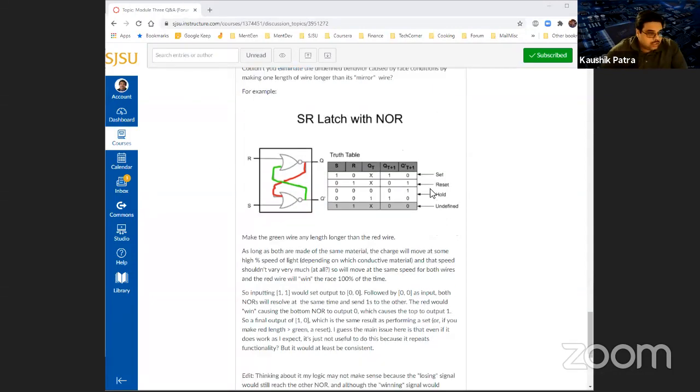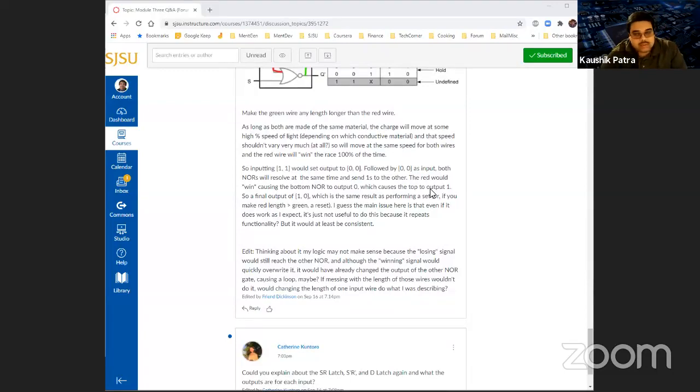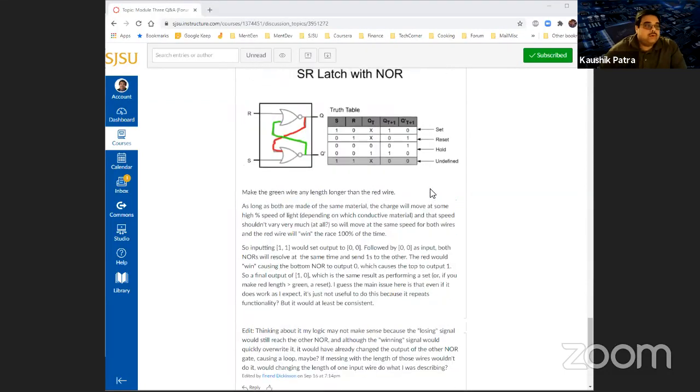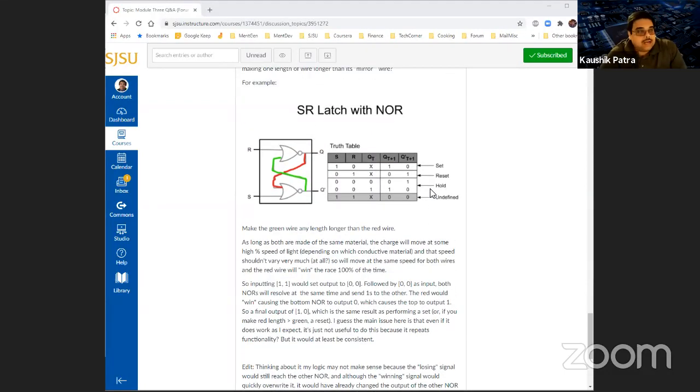That's good thinking. In fact, in asynchronous circuits, some of the reset problems are solved by introducing delay elements between them. Yes, theoretically it is possible to do it, to make one gate the winner over the other. But the point is, why should we do that unless it is absolutely needed? It is all about the return on investment of what you are doing.